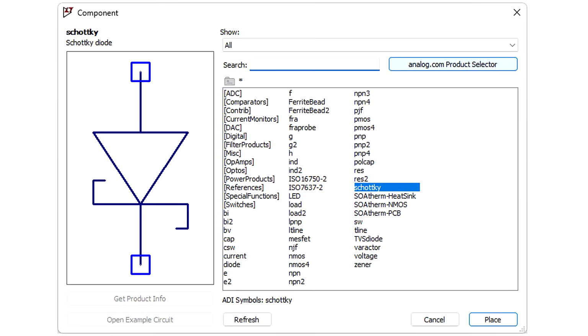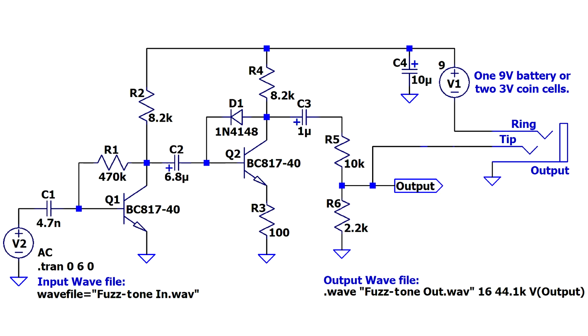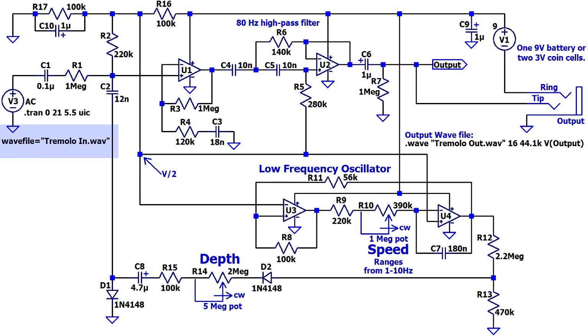Hundreds of components are included, and you can import others if models are available. One huge feature of LT-Spice is it can accept input from a standard WAV file and send its output to a WAV file. This really helps when designing audio devices, so you can actually hear how a circuit performs, not just see waveforms on an oscilloscope display.